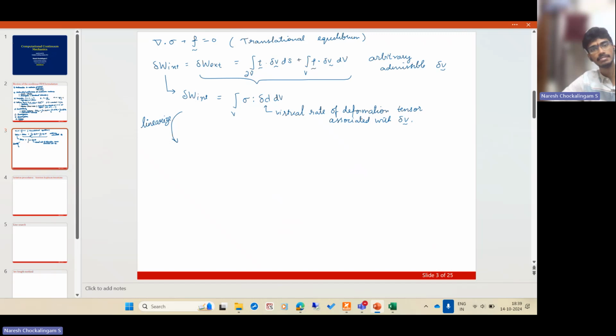The limits of the integration themselves are dependent on the configuration, right? The current volume depends on the deformation itself because it is a deformed volume. Therefore, that will also enter the differentiation. Since that is not easy, we usually linearize in the Lagrangian description and then push forward all the quantities to the current configuration.